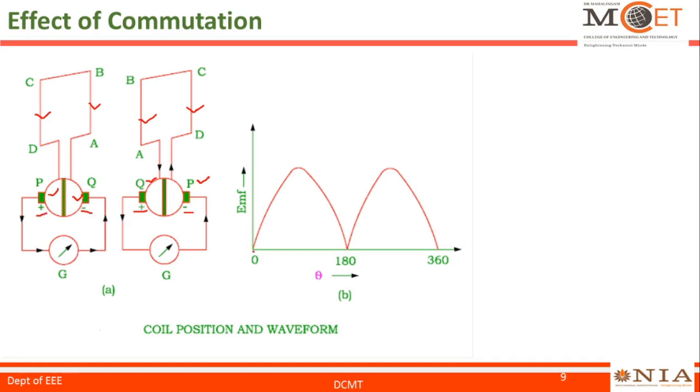So that leads to DC voltage across the commutator segments, or I can say the split rings ensure unidirectional current flow in a DC generator. That is the purpose. We call it the split rings or a commutator, which acts as a mechanical rectifier.